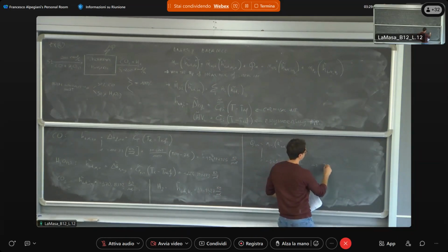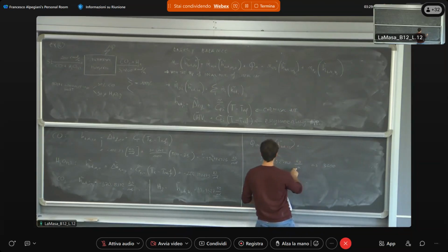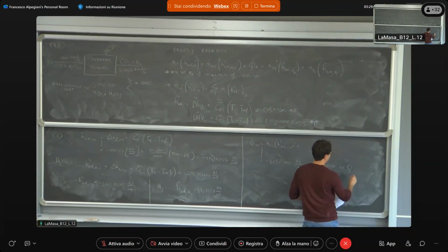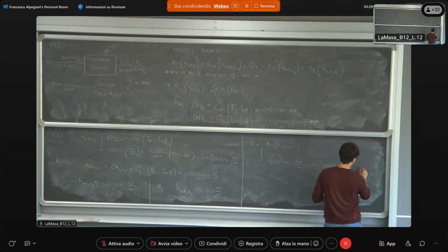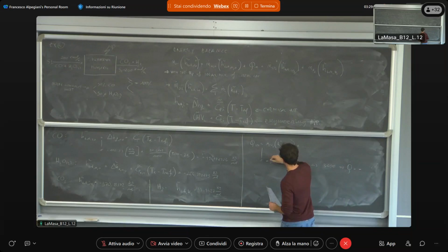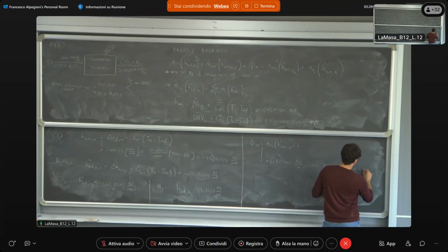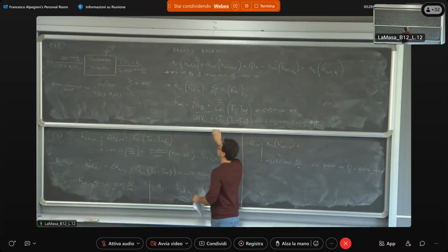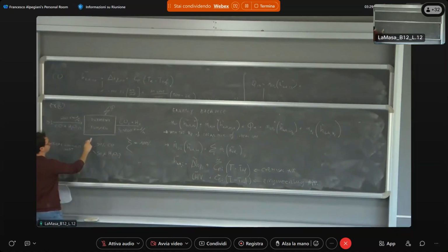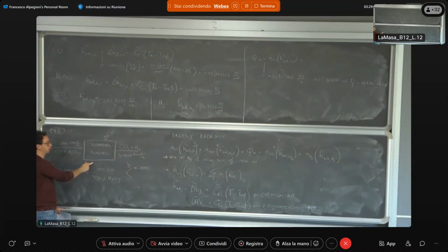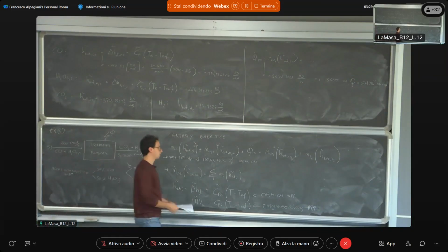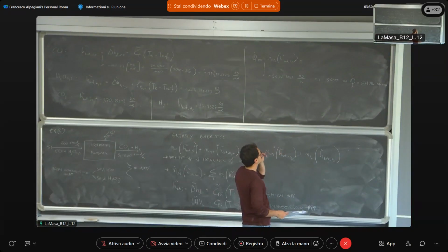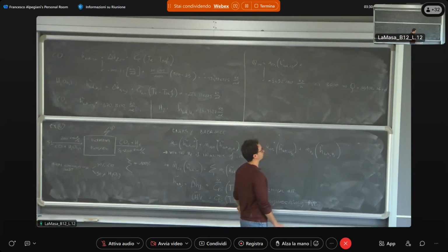Then dividing by 3600 to have this in kilowatt, you obtain a thermal power equal to minus 1014.66 kilowatt. This minus means that the reaction taking place inside the reactor is an exothermic reaction. Otherwise, it would be an endothermic reaction if the sign was positive. Okay.